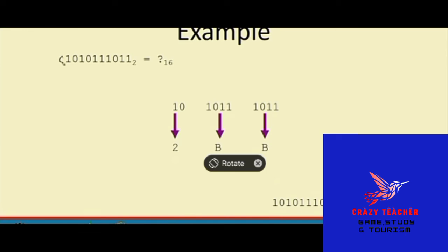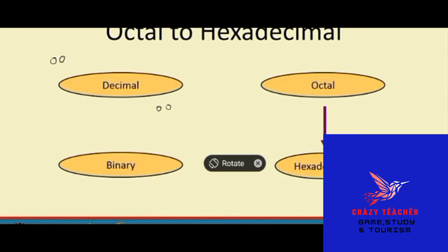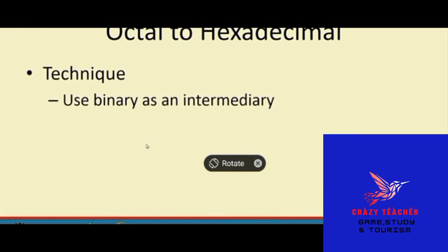Now once the decimal number has been converted to binary, you can do the conversions to other number systems. To convert into the octal number system, we make groups of 3 bits. We make a group of these 3 bits, and then another group of 3 bits for the integer part. So this is 35. For the fractional part we also do the grouping, but here grouping starts from the left side. This is one group, this is the next group. The first group gives the digit 6, and the next gives 3.